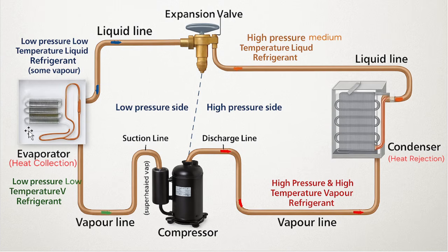That is why we wanted this refrigerant to boil inside the freezer. The refrigerant is boiling inside the freezer, or inside the indoor unit of the AC. Boiling means it needs energy, it needs heat, and inside the freezer it takes heat from the inner environment of the freezer. From the perspective of ACs, the indoor unit takes heat from inside the room. This evaporator is nothing but what you put in the indoor unit. So the actual concept is here.